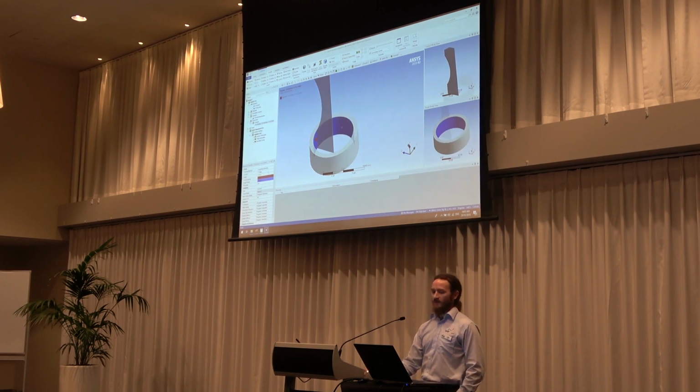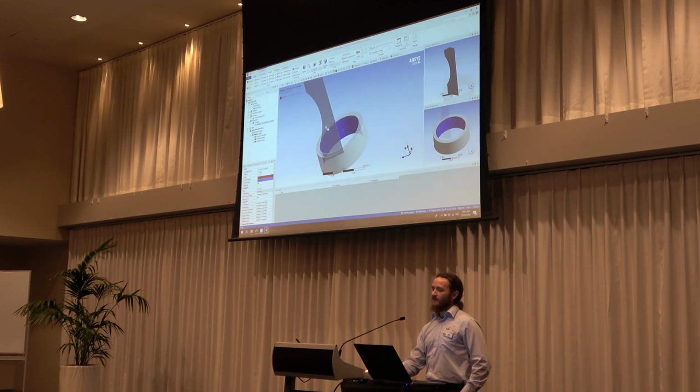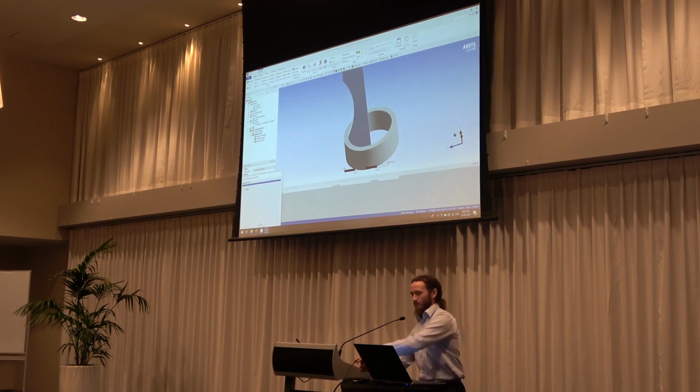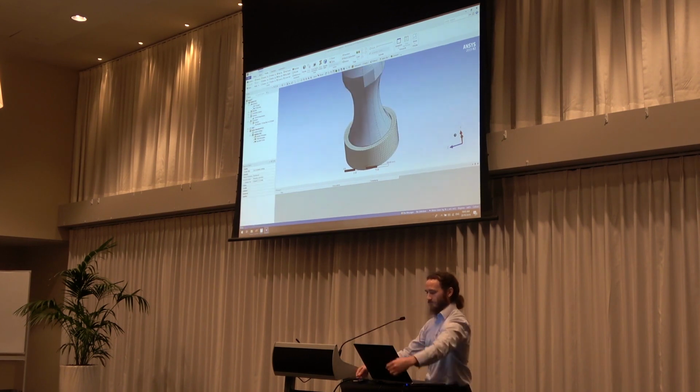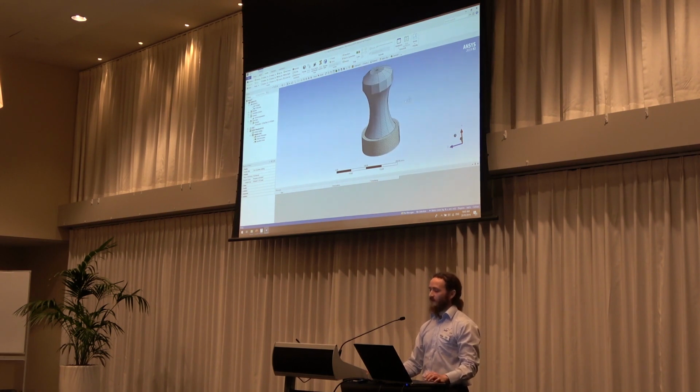So I don't have to go back and forth. It's much quicker and easier for setting up multiple contact definitions. This is going to bond the outer surface of this axisymmetric body to the inside surface of this ring. And then I'll generate the mesh. Right, so there's our 2D axisymmetric body in our 3D world.